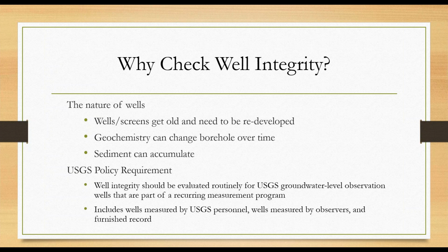So why would we want to check well integrity? I mentioned that we have a policy that states if you have a routine, recurring measurement program, you will do routine well integrity testing. Because of the nature of wells, we will have wells or screens that get old and need to be redeveloped. And you wouldn't know that unless you really check the connection of that well with the aquifer. Geochemistry can change a borehole over time as well, and sediment can accumulate in the well. This is why we want to check well integrity.